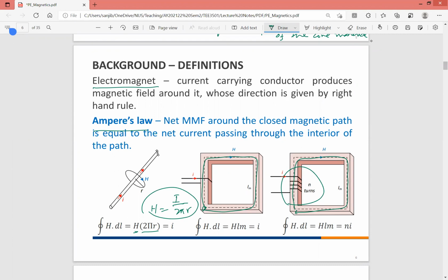So basically, if you have large power conductors which carry thousands of amperes, naturally there is strong magnetic field intensity near that, so that if you have any magnetic material, then there will be large magnetic field induced. But anyway, we can also use the same thing in the case of the electromagnet that we're talking about here. If that integration from Ampere's law, integration of H around the path, if you can assume that the H is uniform because of the way the coils are spread. If it is uniform, it is shown like this, but the coil would be spread uniformly around this.